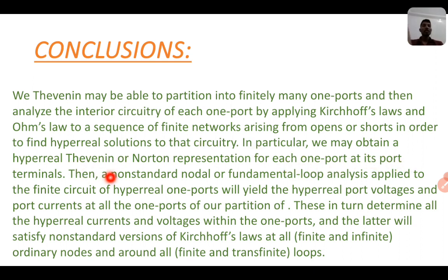terminals, then a non-standard nodal or fundamental loop analysis applied to the finite circuit of hyperreal one-ports will yield the hyperreal port voltages and port currents at all the one-ports of the partition. These in turn determine all the hyperreal currents and voltages within the one-ports, and the latter will satisfy non-standard versions of Kirchhoff's law at all finite and infinite ordinary nodes and around all finite and transfinite loops.